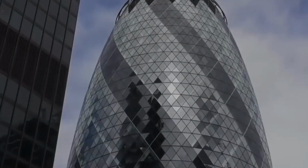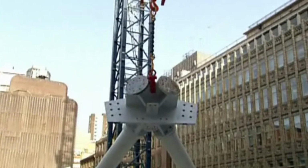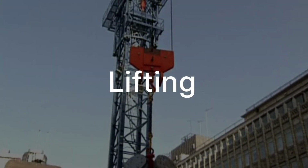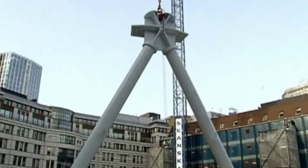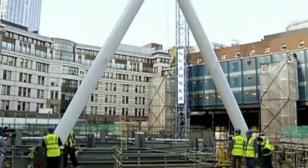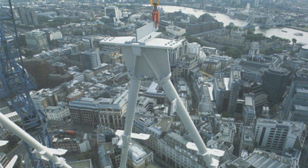The construction sequence of the diagrid structure at Saint Mary Axe is as follows. It goes in the order of lifting, temporary tightening, precision check, and final tightening. Let's take a closer look at each step. First, let's talk about the lifting process. When the huge diagrid components manufactured in the factory arrive at the construction site, they are lifted up to the installation position using a tower crane.